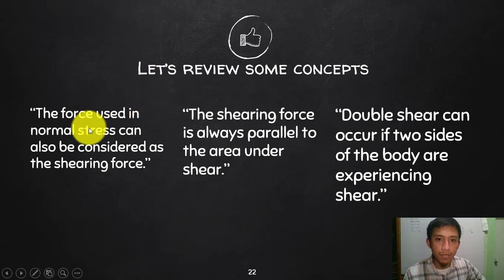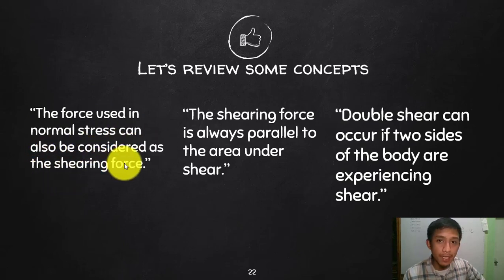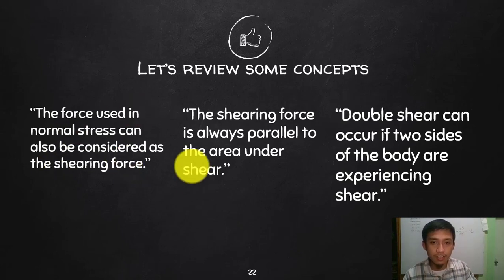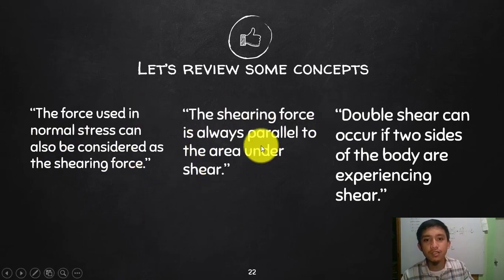Okay, so let's review some concepts on shear. Shear stress: the force used in normal stress can also be considered as shear force. So again, the force will not determine the type of stress. The type of resistance, how will the area resist? Is that area resisting by means of tension or compression? That is perpendicular, therefore that is normal or axial stress. Or will that area resist by friction? So the area should be parallel. So that is shear. So it says there in the second concept that the shear force is always parallel to